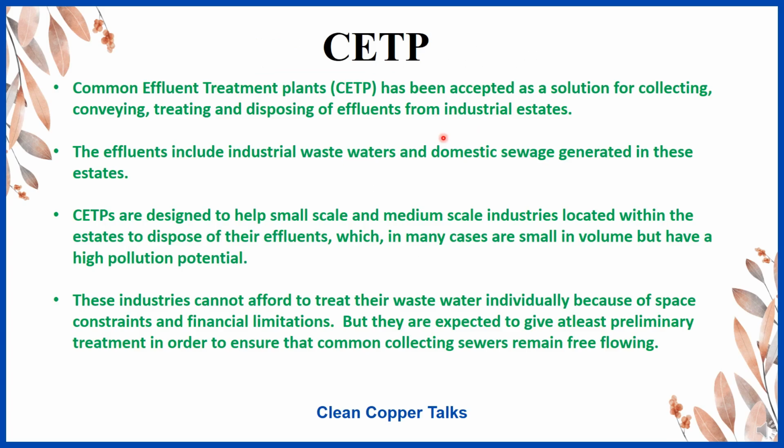So common effluent treatment plant, as the name suggests, is a treatment facility which is common for a number of industries, usually small and medium scale enterprises. Common effluent treatment plant is an effluent treatment facility where a large number of small and medium enterprises send their wastewater to be treated. It has been accepted as a solution for collecting, conveying, treating, and disposing of effluents from industrial estates. The effluents include industrial wastewaters and domestic sewage generated in these estates.